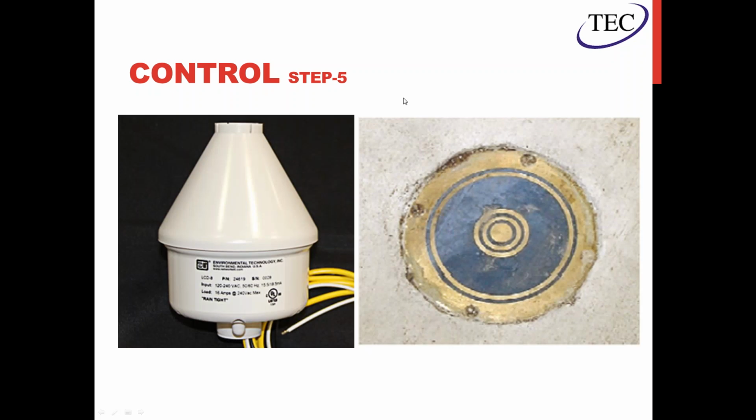So what that means is, quickly here, the left is what they call an aerial sensor. It's mounted outside, either on the top of a building or on a post. When snow starts falling, it collects snow in the cone on the top here, and there's a sensor pad on the inside that senses the snow.